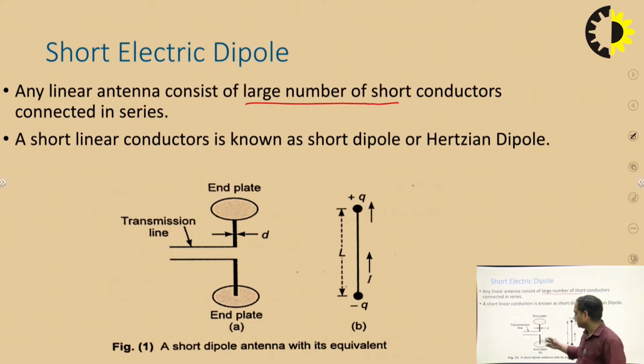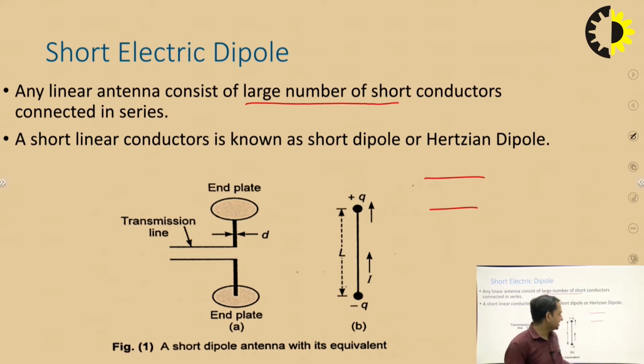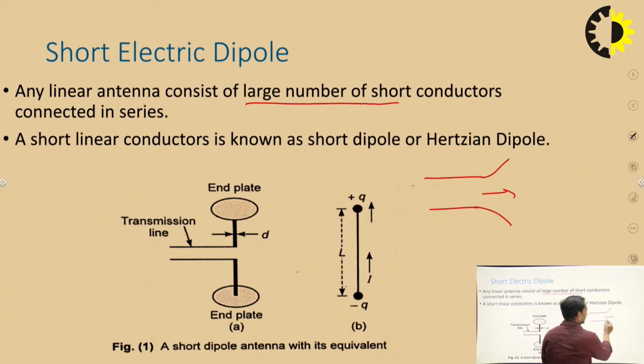So as we know, when we have two lines like this, two wires or a transmission line or coaxial cable, it cannot transmit the signal into the air, into free space. If we have parallel lines, they cannot radiate the signals. So what do we need to do? We have to do some flaring at this end, right? Because of that, the antenna can transmit the signal.